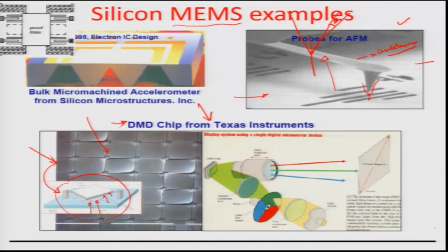So, there is a tendency of this mirror to rotate about this pivot point, and the mirror of course is a reflector. Let us say there is a beam of light which falls on such a chip, which is an array of such mirrors, and one of the mirrors rotates out of focus. This is where the beam gets guided into this particular lens here, which projects it on a bigger screen by magnifying the image. Now, supposing there is a beam which goes out of place and out of this focus.